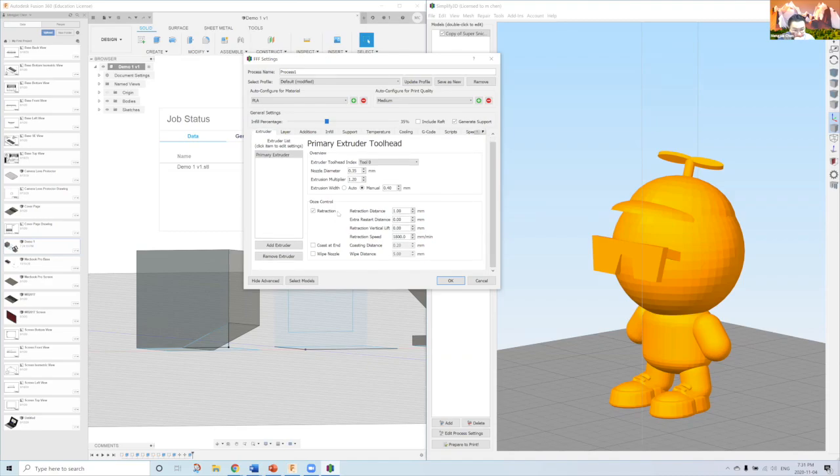Here's the retraction settings I was talking about. So here's the retraction distance, right? You can retract for 1 millimeter, you can retract for 10, depending on the printer. So the two FDM printers I showed, the first one, right, had the extruder in the back, right? And it uses a tube, filament tube, to push the filament through. What happens there is that there is a tolerance, right, for the tube that the extruder has to compensate for. So the retracting distance for that printer will be larger than what you have for the second one, where the extruder is directly above the hot end.